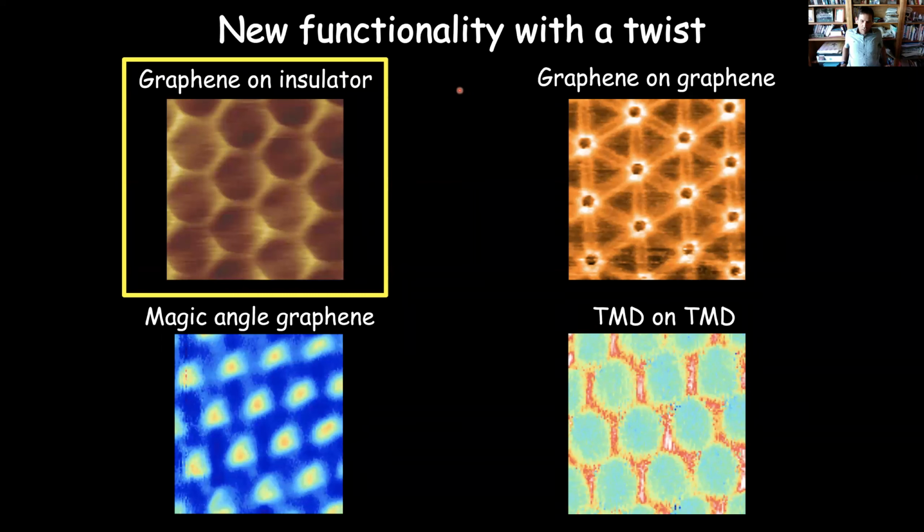So the first way is we vacuum anneal the devices. So the residue ends up only being on the top of the first layer, because the PC comes in contact with the first piece that we pick up, and then every piece that we pick up subsequently is only coming in contact with the previous one. So only the top one comes in contact with the PC. So when we're done making the stack, we can just vacuum anneal that and get rid of the residue there.